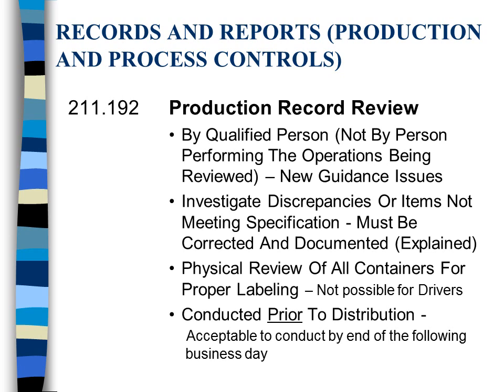Again, that can't happen if you're on the route making a delivery for an oxygen reservoir fill or a nitrogen dewar fill. That is done post-fill. Anything that is filled in the plant, whether it be nitrogen NF or liquid nitrogen, liquid oxygen, or oxygen USP high pressures, has to be conducted prior to the distribution of that product. The QCU member must review the production logs and the cylinders themselves to ensure that they are properly labeled, properly filled.